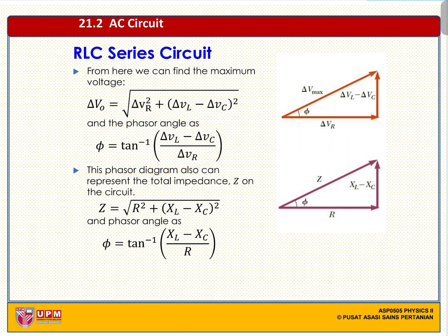So, if you get a positive phasor angle, it means your VRLC leads the current. If you get a negative phasor angle, VRLC lags the current. It will be left behind. If positive, it will be ahead. So, this one, you know this part is equal to I naught, the total one, the total resistor. This is your total resistor, we will use it as Z.